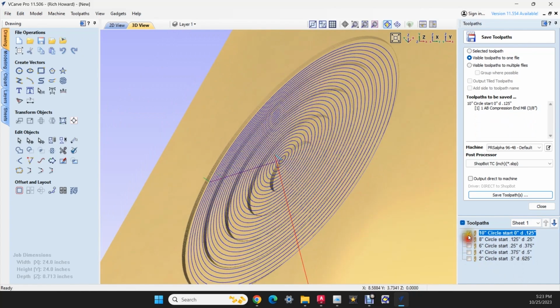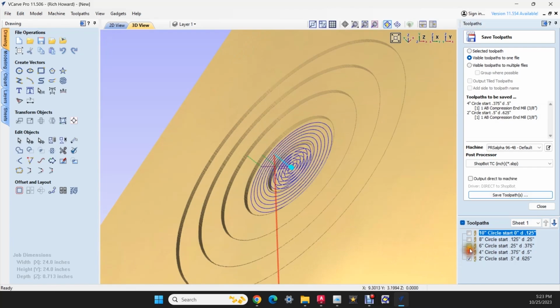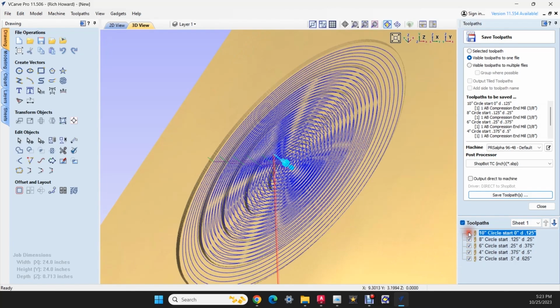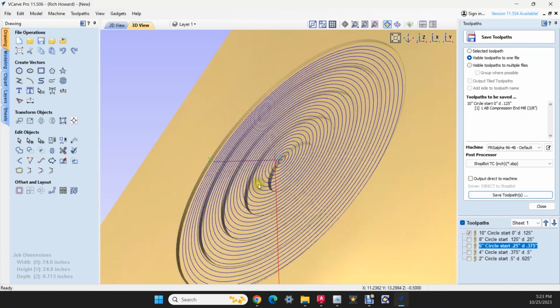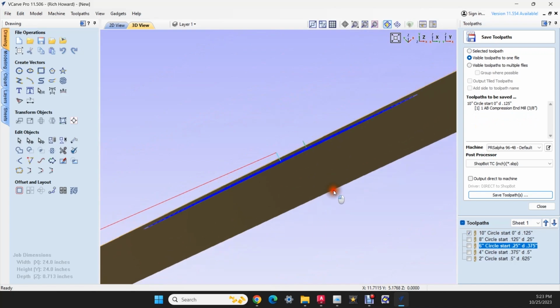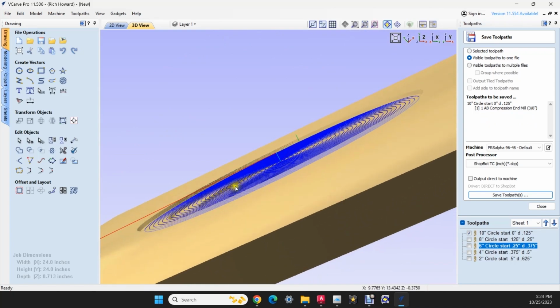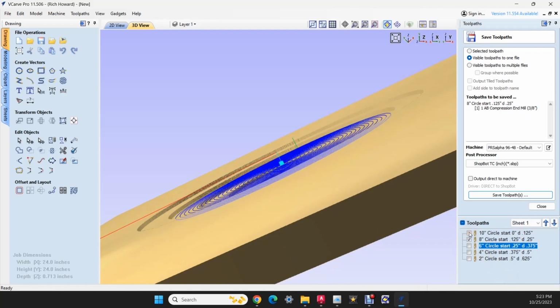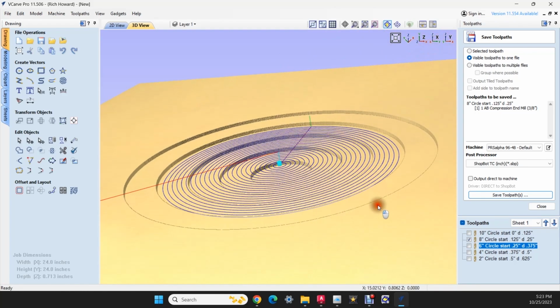We'll get rid of these tool paths. All right, a 10-inch tool path. Yeah, this is great. All of the lines, they don't change the depth at all. Let's throw in the 8-inch, get rid of the 10-inch. And all of those lines are clearly not up at the 10-inch level. And you probably know this, but the red line indicates where the tool's coming from.